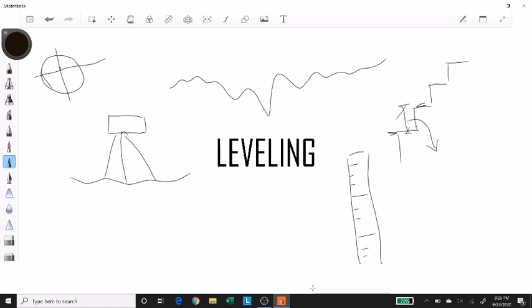So when you look through the auto level instrument, you get a line of sight. This is an imaginary line, which is called your line of sight or line of collimation. When you're looking through this instrument, standing on one side, what you're actually looking at is this crosshair with a telescopic vision, which magnifies it, and on the end of it, there you place this leveling staff.